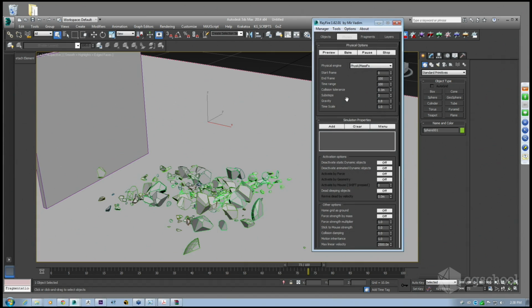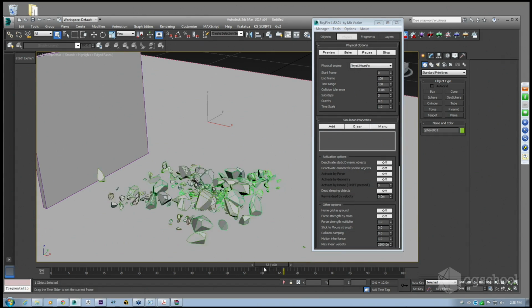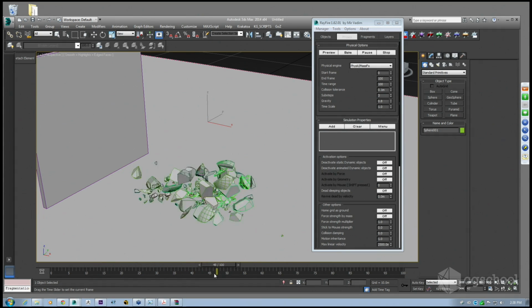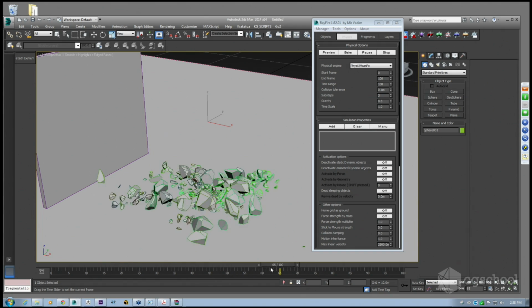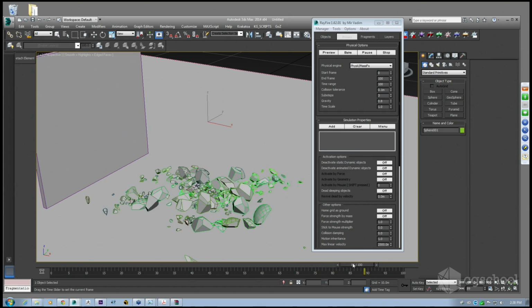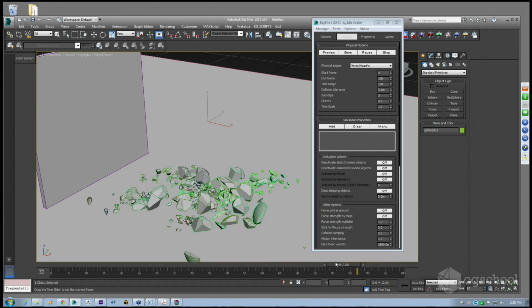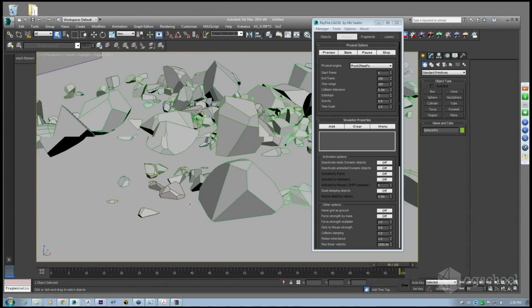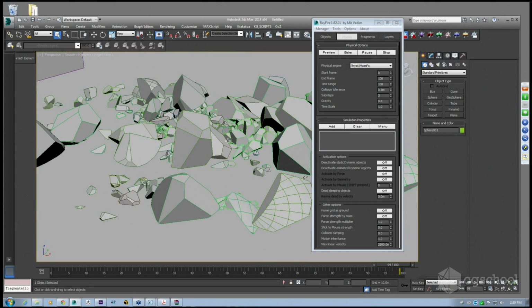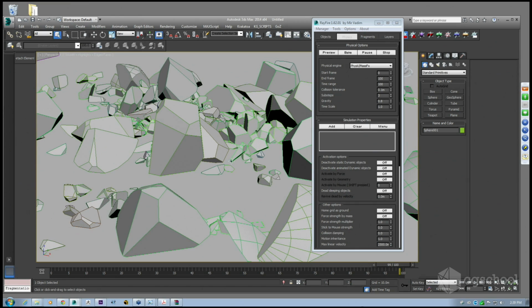Now, to make this simulation a little bit better, we have a few things popping around. It's not too bad, but if we wanted to make this slightly more accurate so that objects are colliding a bit more accurately, or they come to a stop a little bit sooner, the settings within the physics system add to that. And this is similar-ish to how physics works on its own, or Mass Effects works on its own. So we can change our collision tolerance. This will basically say between materials how close their RayFire mesh that it puts around it allows them to collide.